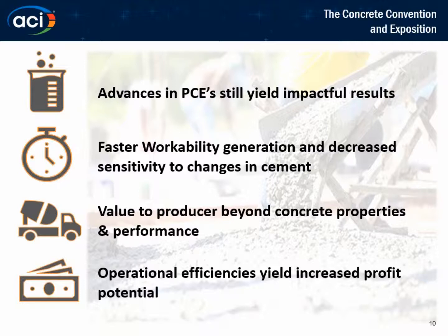Yes. Is there a difference on the compressive stress? Impact on compressive strength. We saw improvements in the overall compressive strength, especially at early ages, and our hypothesis is that because of the increased efficiency of the dispersion itself, you have a better dispersed mix, which hydrates your cement more efficiently, providing you generally better compressive strengths at all ages.